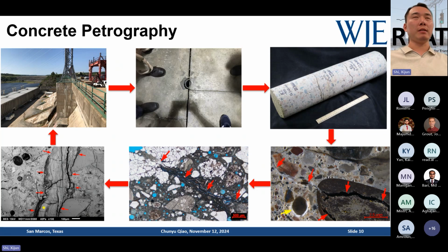This whole structure has experienced ASR deterioration for decades. You can see in the middle of the image, the engineers normally have to do a very detailed on-site inspection of different parts, of the condition of the whole concrete structure, and so on and so forth. This routine inspection has been ongoing for decades. Engineers have constantly given advice, saying ASR is an internally expansive reaction, right? So the whole structure, your concrete shell or concrete member, is trying to expand, and you want to release this expansion. How do they do that?